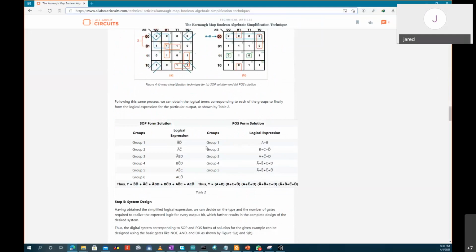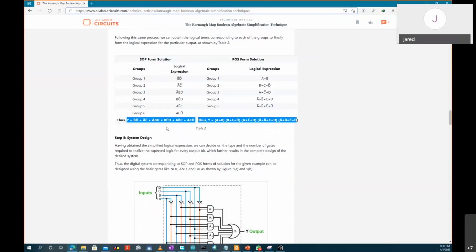And from there you see what we're coming up with. This is expression group 1, group 2, and so on. So this is now the output for our expression. This is now what you'll feed into the PLC. You'll feed this function to the PLC. You see, this is not fully simplified, but now this is the actual simplified version, the final. So now when you load it to the PLC, you just have A, B, C, D. You put a NOT, and you get your output.